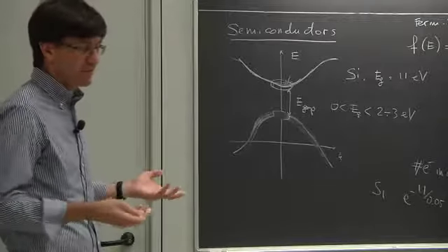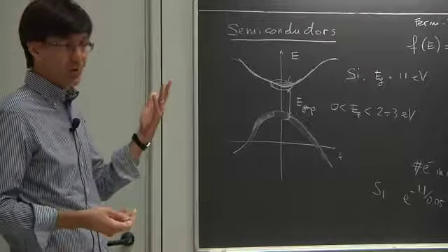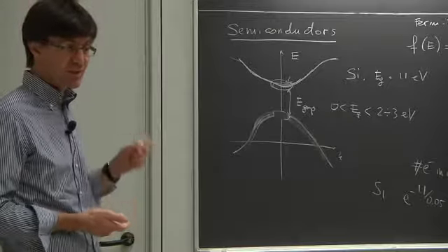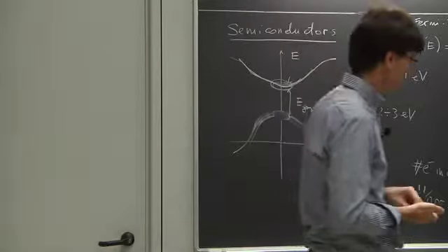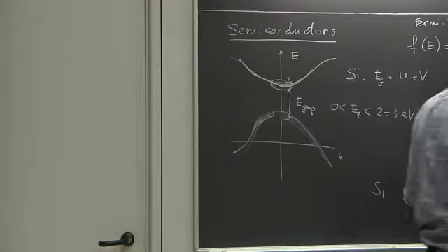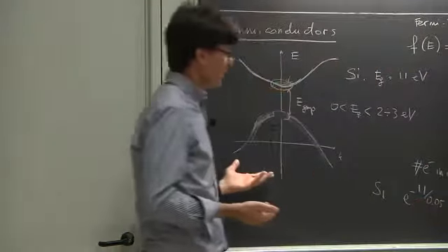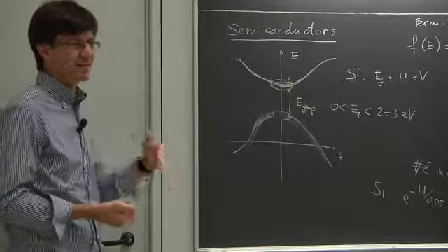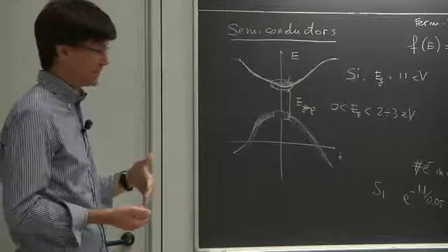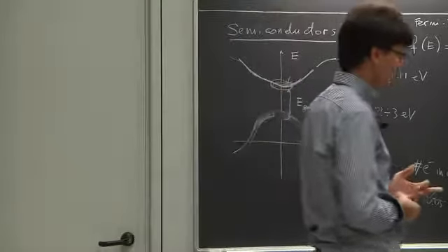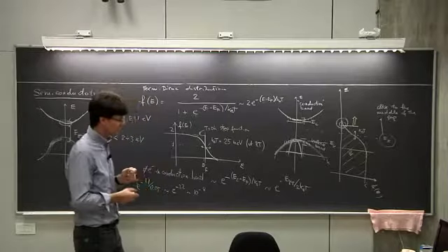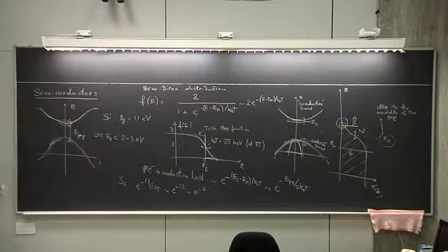That means also the conductivity of the system has increased by an order of magnitude, just by changing the temperature by 10%, 30 centigrades. So the resistivity of a system like this, even though it's extremely high resistivity, conductivity extremely low because there's no number of carriers, it is extremely sensitive to temperature. So small changes of temperature can change the conductivity by orders of magnitude, which is one important property.